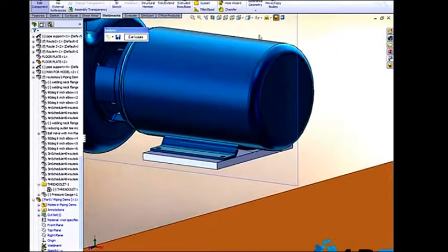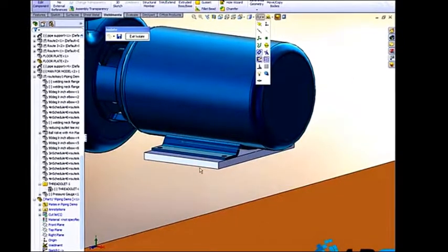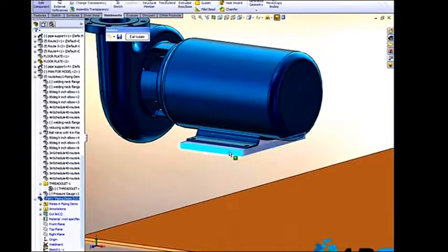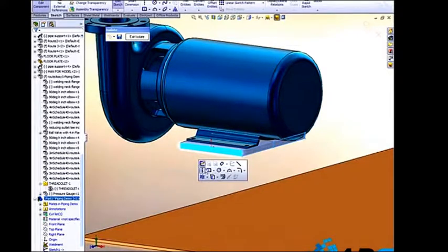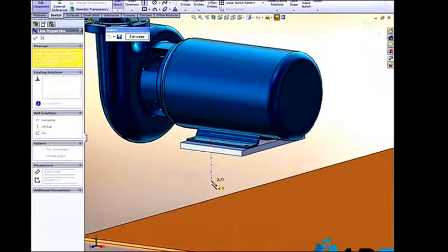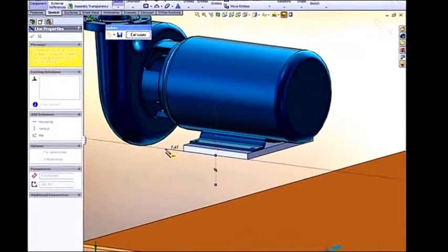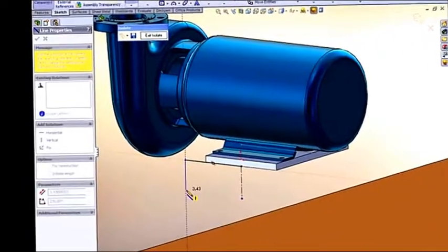Now we're going to define the rest of our weldment structure. We're going to do that by sketching on the side face of the plate we just created. For this sketch we just want to draw half of it. So we'll put a center line down, and we'll use that later to mirror our geometry to the other side. Here we'll just go in and sketch out the shape that we want to achieve.